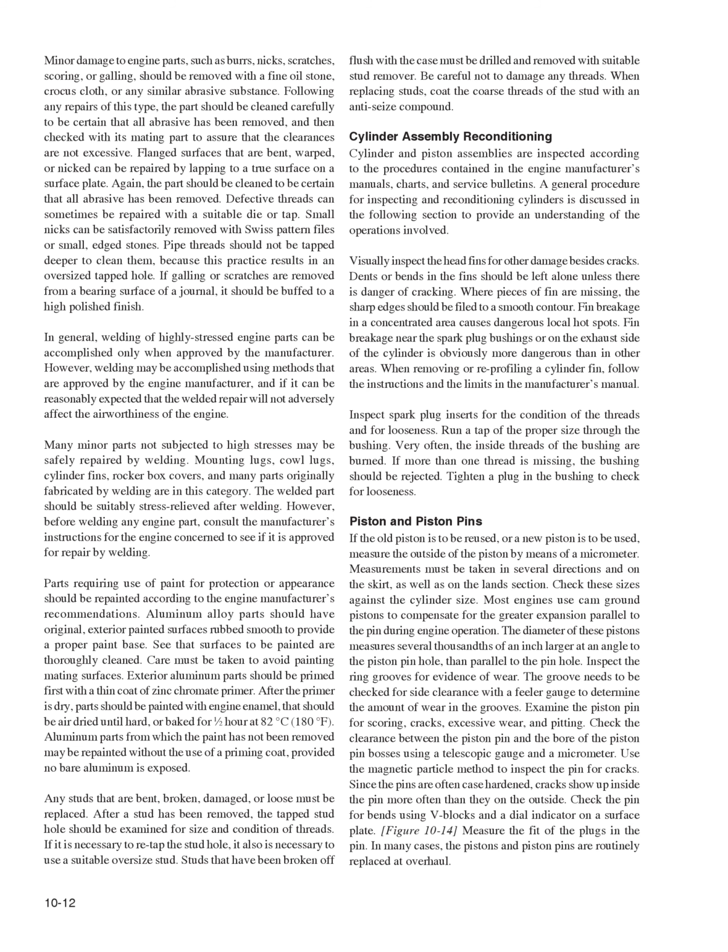Aluminum parts from which the paint has not been removed may be repainted without the use of a priming coat, provided no bare aluminum is exposed.